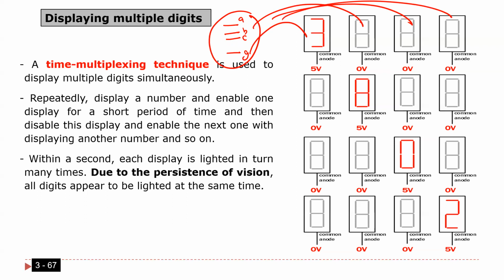Is that okay? Also, I'm gonna use the common anode for enable or disable. So all I need right now is 7, or 8 because the 8 is the dot. Anyway, I'm gonna say 7. So I need 7 plus 4 pins for enable or disable, as you see here.